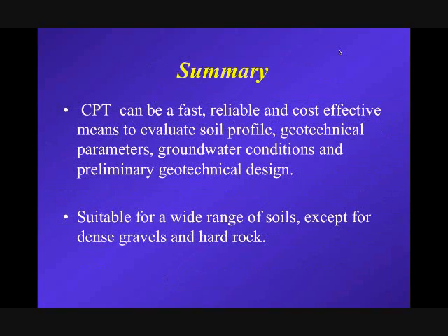So in summary, the CPT is a pretty fast test. 2 centimeters a second, roughly a meter a minute. You can do a 30-meter sounding in and out in less than an hour. It's pretty reliable. It's essentially operator independent. You get essentially the same result if you move over and repeat the test, or if you bring in a different contractor. Very cost effective because it is fast, particularly if it's locally available.